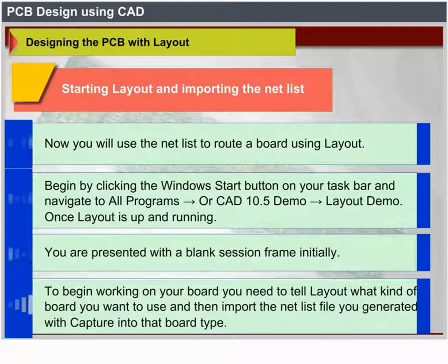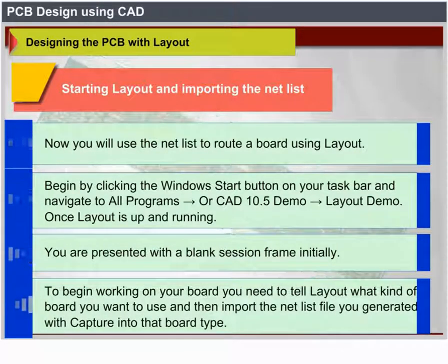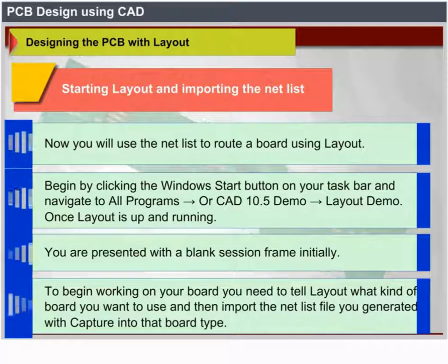To begin working on your board, you will need to tell Layout what kind of board you want to use and then import the netlist file you generated with Capture into the board type.